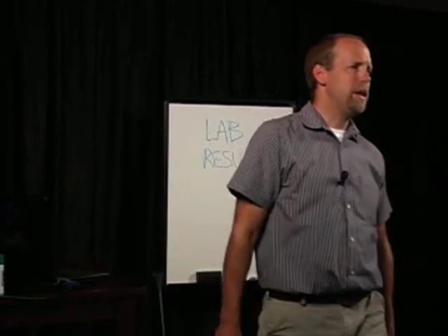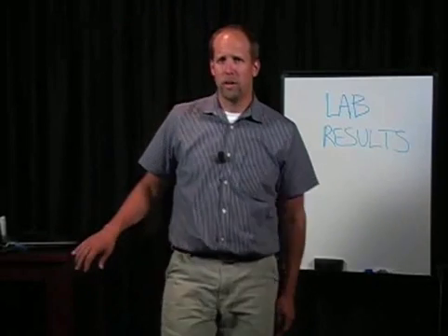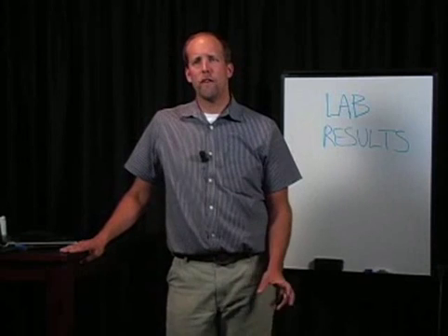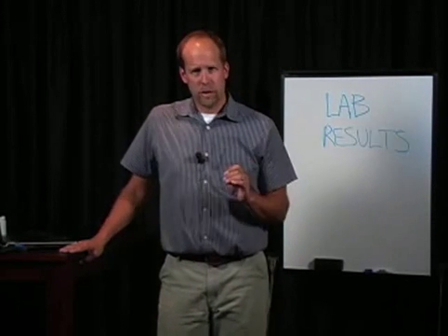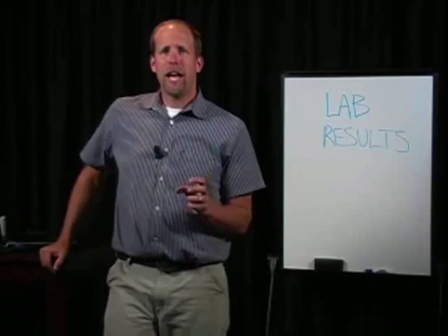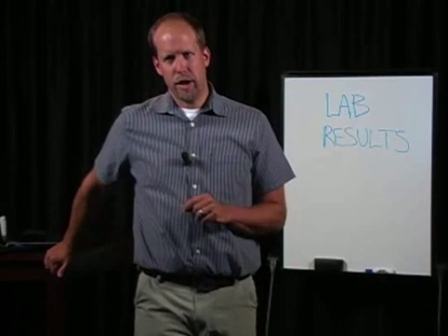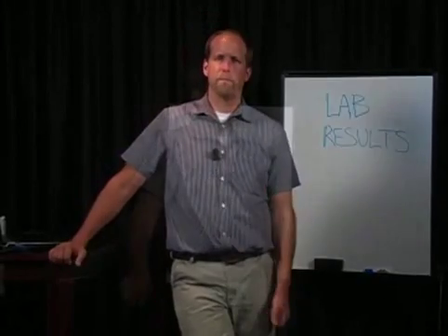Mold should not be permitted to grow and multiply indoors. Problems associated with mold have been around since recorded history. Solving mold problems requires fixing the source of the moisture and removing any contaminated components. In remediation, you have to dry quickly. Dry items before mold grows if possible. Mold can grow instantly if there is adequate temperature, moisture, and food provided.